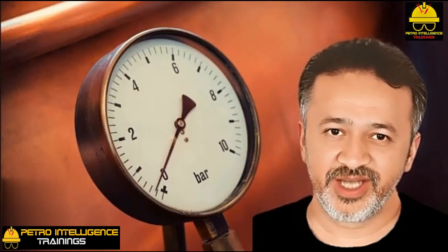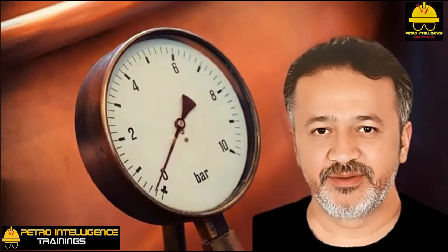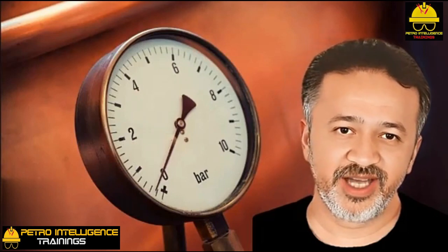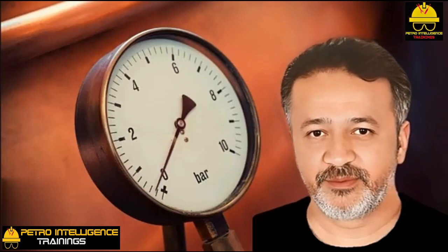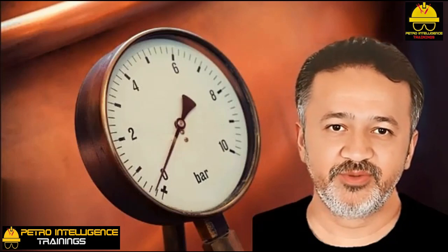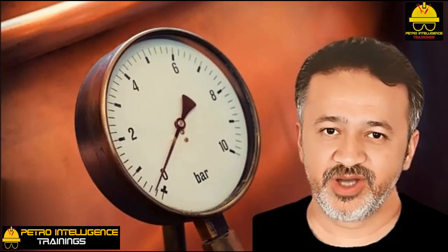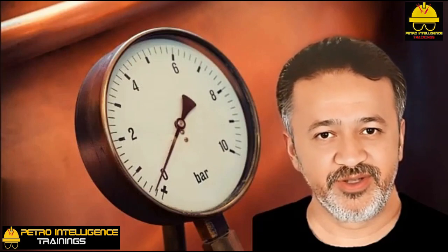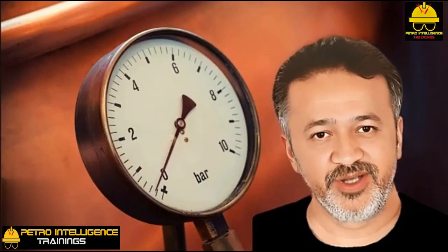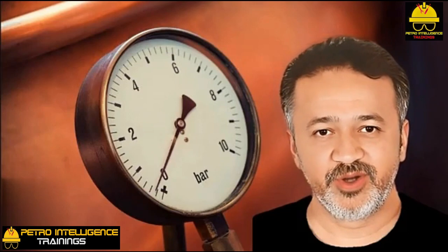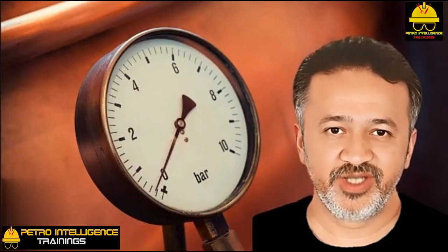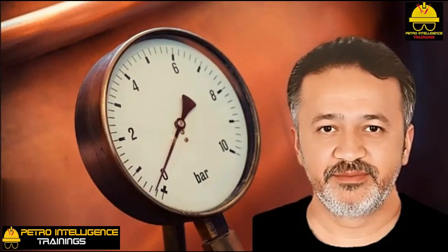This type of gauge, if zeroed at sea level in New Orleans, will read 4 inches of Hg vacuum in Denver. Most pressure signals transmitted from the field into the control center are generated from pressure transducers. Differential pressure indicators simply take the differential readings from two transducers and generate a milliamp output signal.